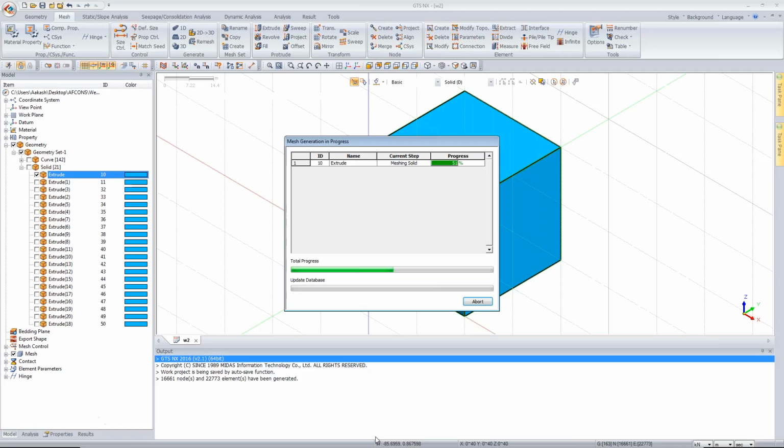Once the meshing is done, I will show you how exactly the nodal connectivity is also taken care of. Whatever mesh size you give the inner excavation, a size of 0.2, you give the outer solid mesh a size of, let's say, 4 or 5. Many times, if you don't perform the nodal connectivity, the nodes will not be properly connected.